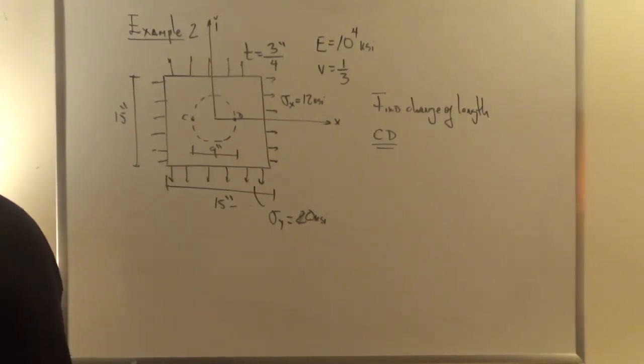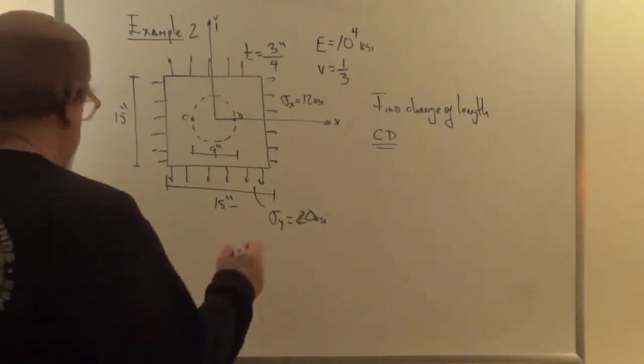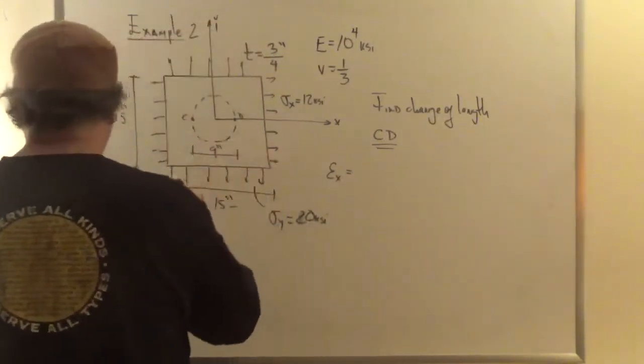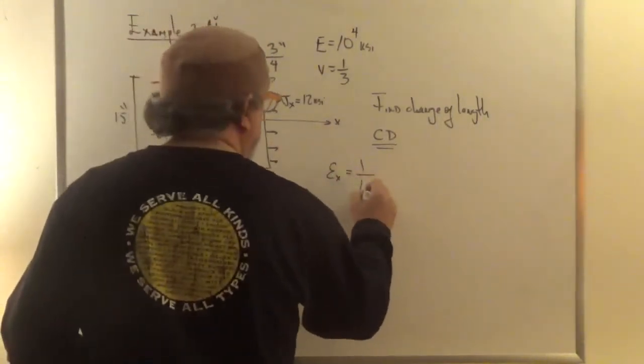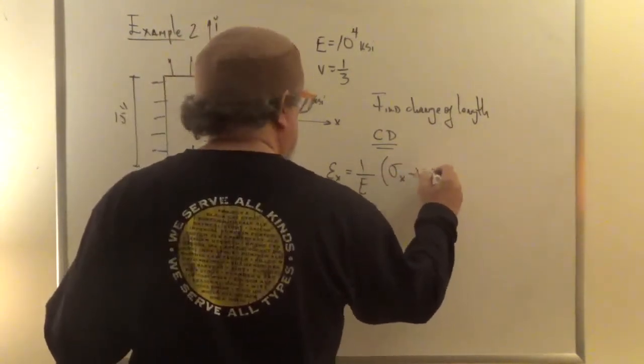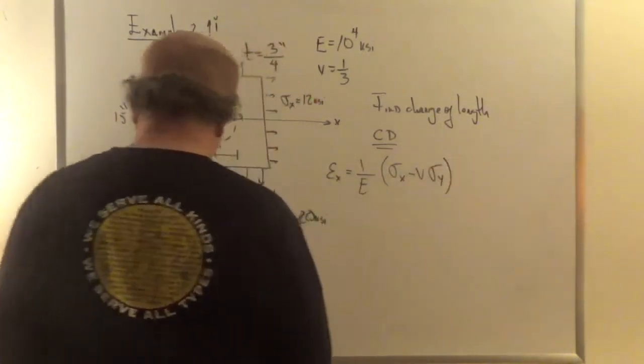Based on plane stress, my strain in the x direction is equal to 1/E, this is a simplified version, sigma x minus nu sigma y, right?